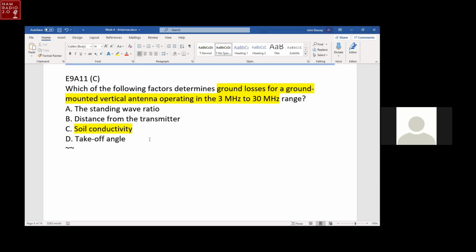Okay, so on the Buddipole system, if you make a vertical antenna out of it, on the red pin that you connected to the antenna itself, then you have a black pin that is supposed to go to a counterpoise. And a counterpoise for those kind of antennas, you usually get it with it. It's a big long wire that you make a quarter wavelength out of it and then stake it to the ground, physically to the ground.